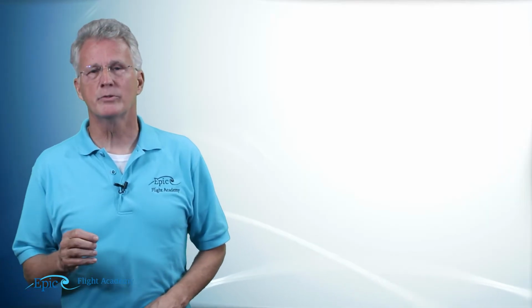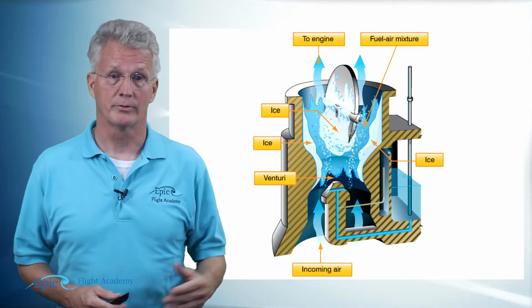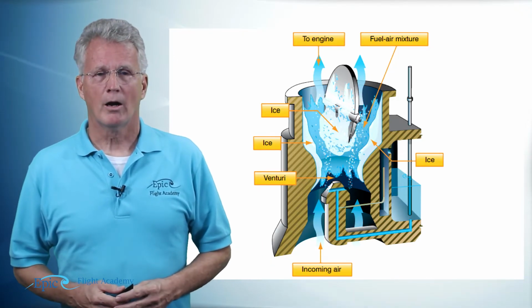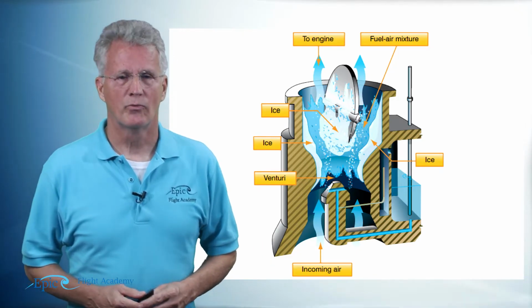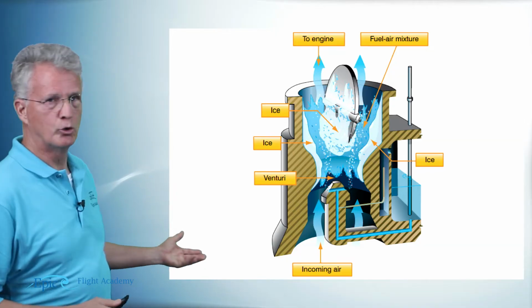Now, this carburetor is very reliable and works flawlessly over a wide range of conditions. But there is something that you need to learn about, and your flight instructor will introduce this to you, and you'll learn more about controlling it if you're operating a carbureted engine. And that is carburetor ice. Carburetor ice forms in this Venturi,